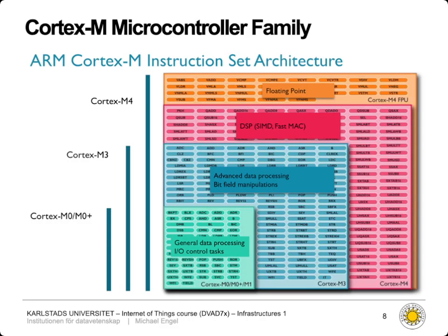And DSP functionality includes things you might need to accelerate, like cosine or Fourier transforms, for example, a separate multiply and add instruction, which does it in one cycle, which accelerates your typical FFTs. So if you need to do a frequency domain analysis or transformation, this is accelerated significantly. So essentially, you get quite a large number of features, which can be very useful here.